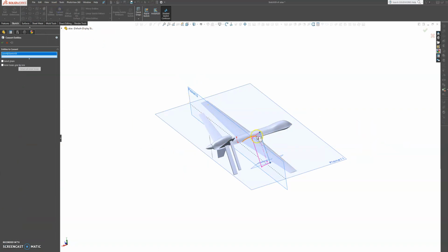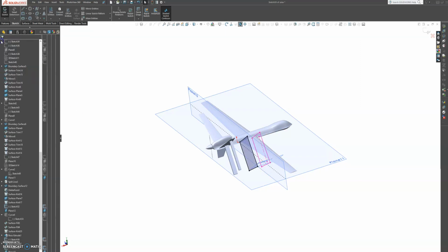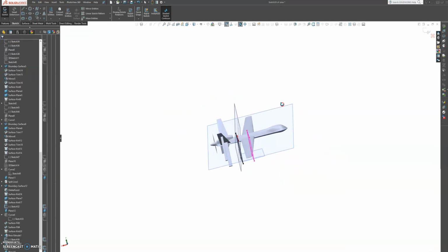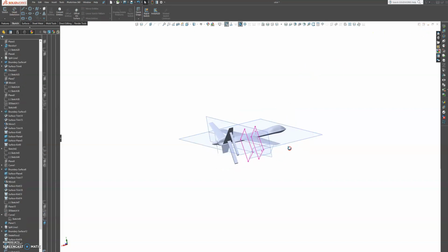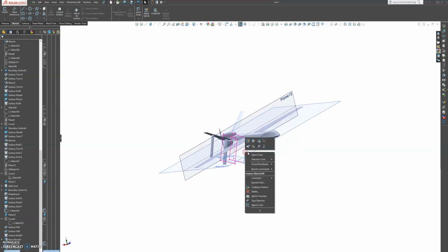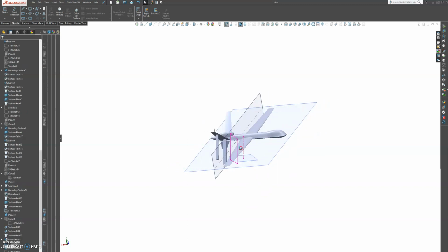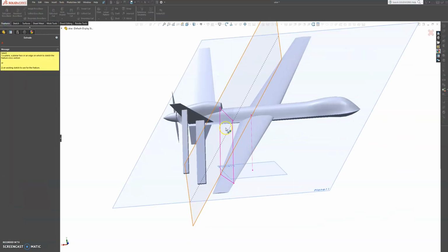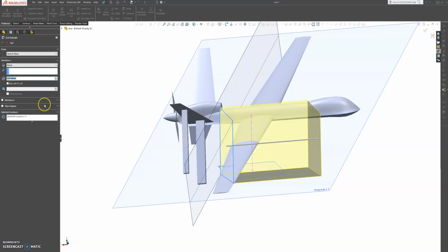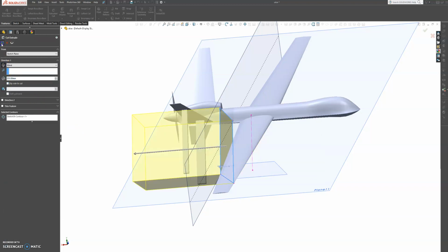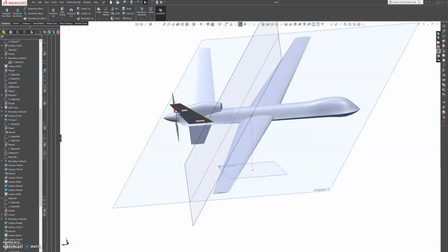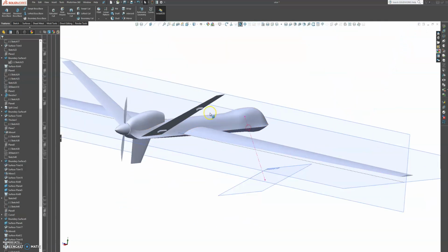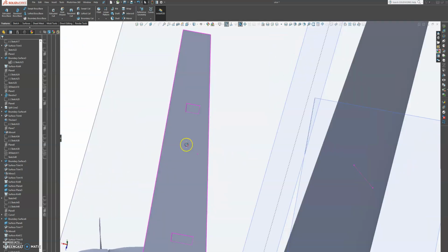Let's select this sketch. Okay, let's select that. That's a lot better. Okay, exit the sketch. Okay, let's hide that, we don't need that. Okay, good. And now we go to features, extrude a cut, select this sketch, the other way around, cut that off, and bam, good.